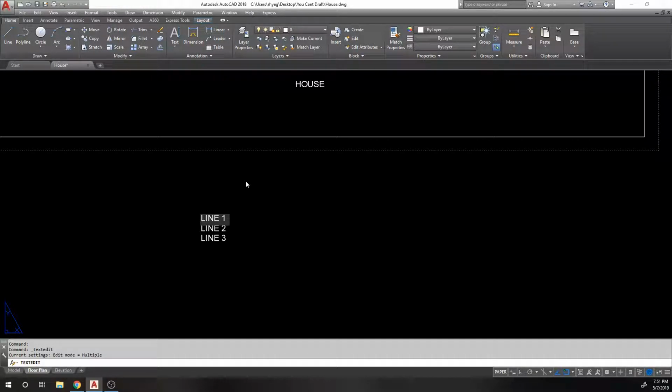Or you can do the other kind, which is I think holding Alt and typing something like 0216, which will create the diameter symbol. I think Alt 0172 does, or 0176, I can't remember which one it was, something like that creates the degrees symbol. AutoCAD also has special functions like %%C will do diameter, %%D will do degrees, %%P will do plus or minus.